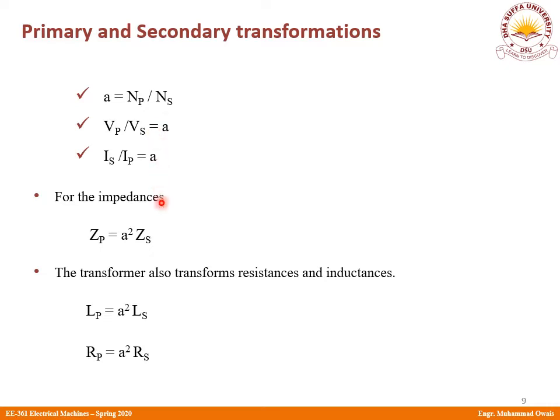Before we proceed and continue with our discussion on equivalent circuits, and you shall see we will be discussing different types of circuits which model the transformer, this is just a summary of a previous relation which we have used frequently. This was the relation Zp is given as a squared times Zs, where Zp is the impedance at the primary side and Zs is the secondary.